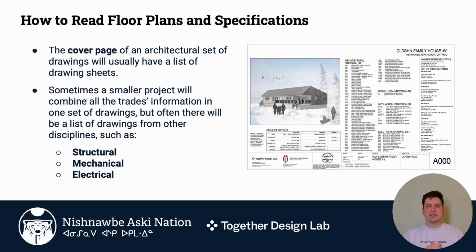What you see on your screen is a cover page, and usually the cover page in a construction drawing set or an architectural drawing set acts as a kind of table of contents, working you through everything that you're going to find in that set. The one you see on screen was created from the same project that is supporting this course, Community-Led Design for Specialized Housing in the North, and it's one of the family housing sets. And what you can see along this area is all of the different drawings that are included.